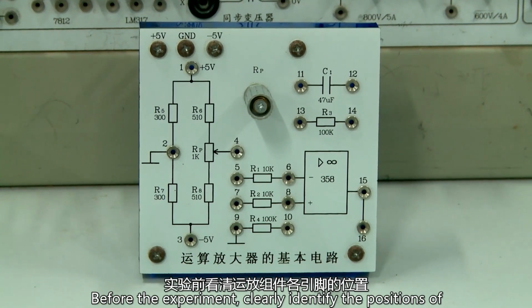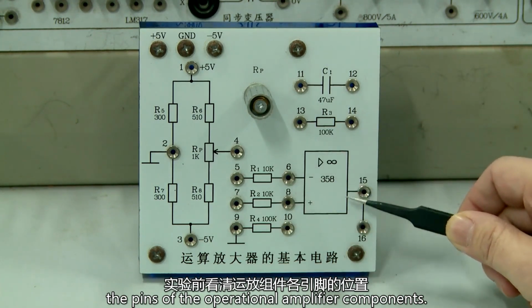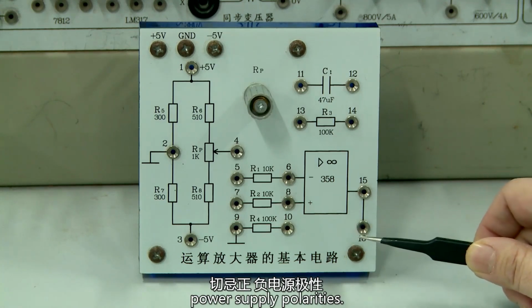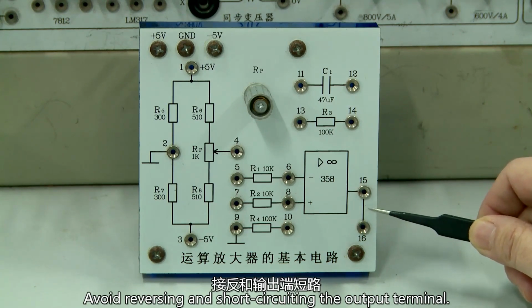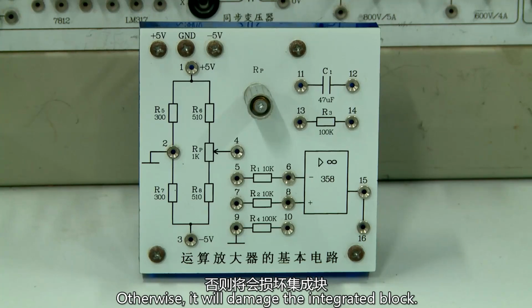Before the experiment, clearly identify the position of the pins of the operational amplifier components. Avoid reversing the positive and negative power supply polarities. Avoid short-circuiting the output terminal. Otherwise, it will damage the integrated block.